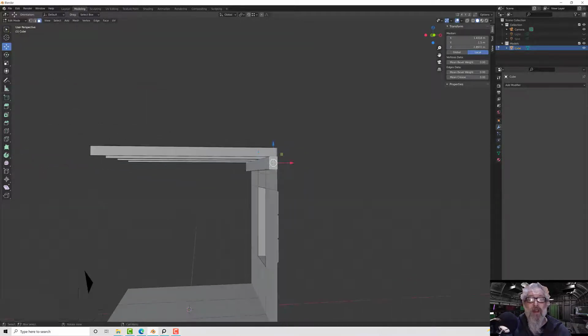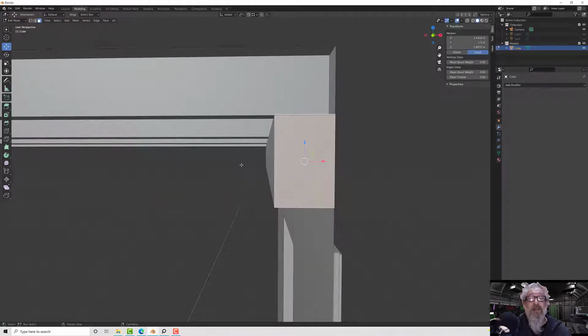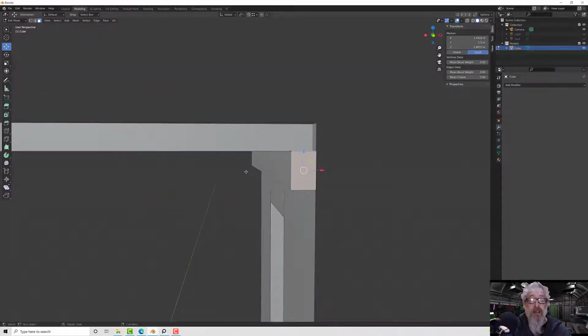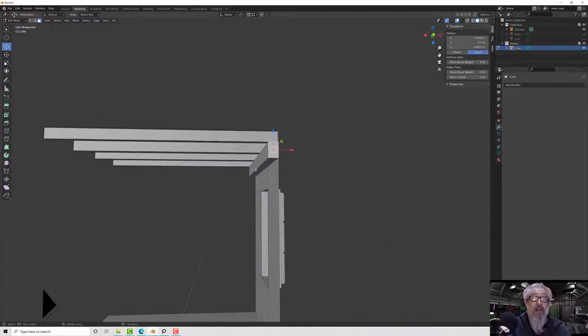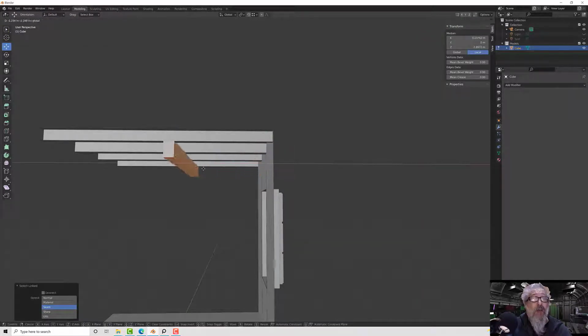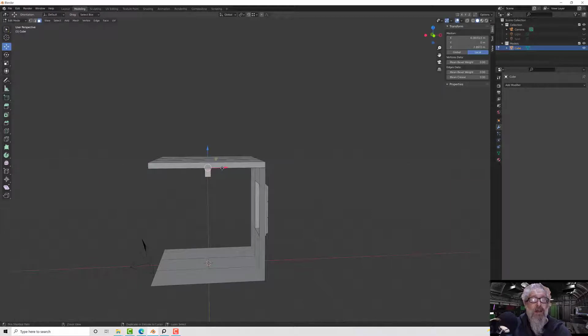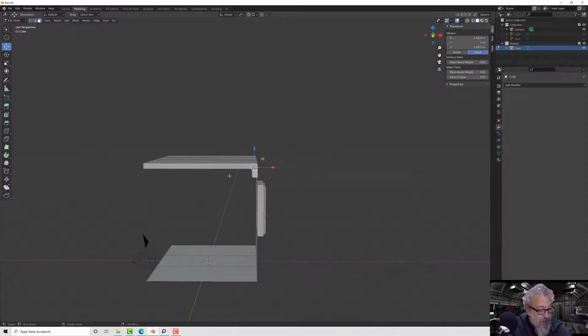Okay, so this is great, but I don't want to delete anything out yet because I'm going to duplicate it. So let's grab this actually and press L, and I'm going to move it to about halfway down our model, providing I remember to press Shift D first, John. Shift D, there we go. Right click and then move.